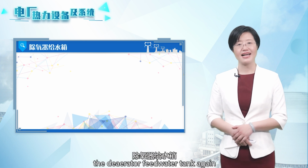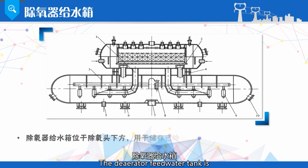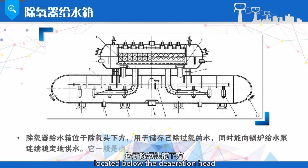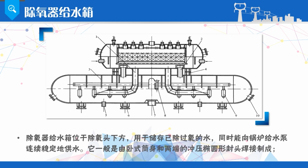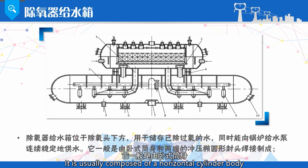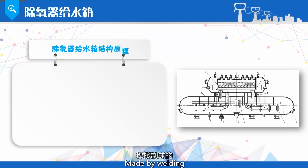Let's take a look at the deaerator feed water tank again. The deaerator feed water tank is located below the deaeration head, used for storing water that has been deoxygenated. At the same time, it can provide a continuous and stable water supply, like a boiler feed pump. It is usually composed of a horizontal cylinder body and stamped elliptical winged heads at both ends, made by welding.